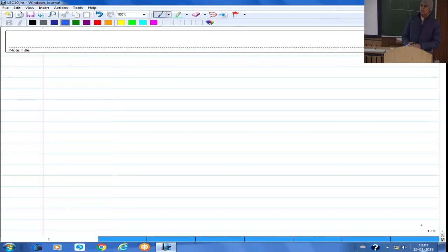Yeah, if it is at an angle, you will have two components, and the component along the length of the member is basically axial force, but then you will have a transverse component of that force which will lead to bending also.